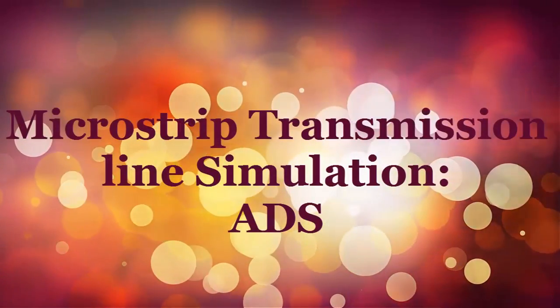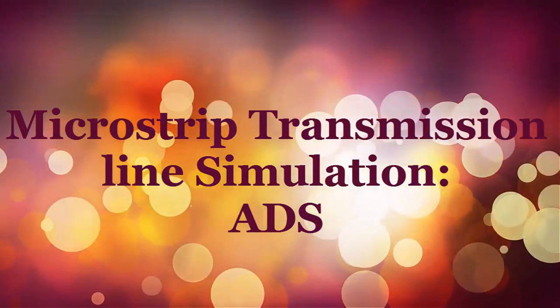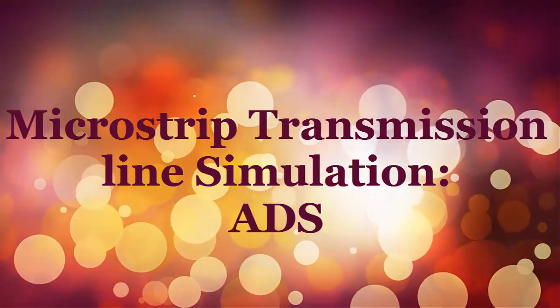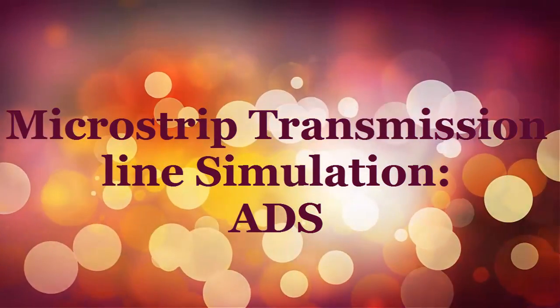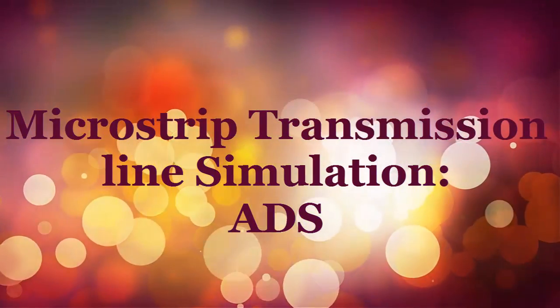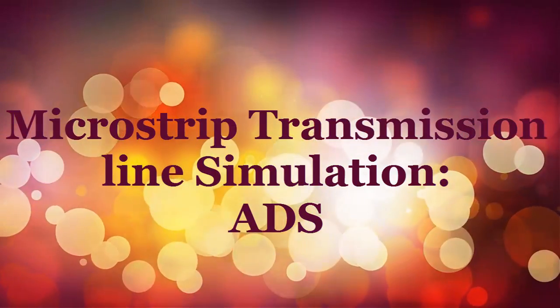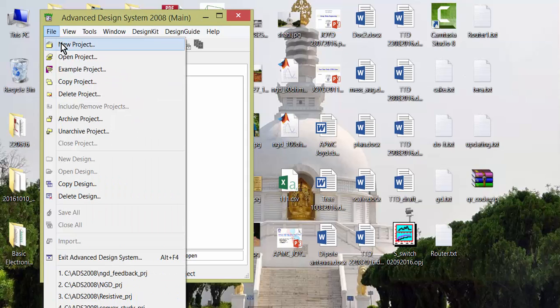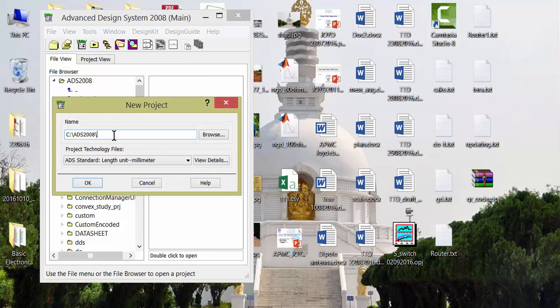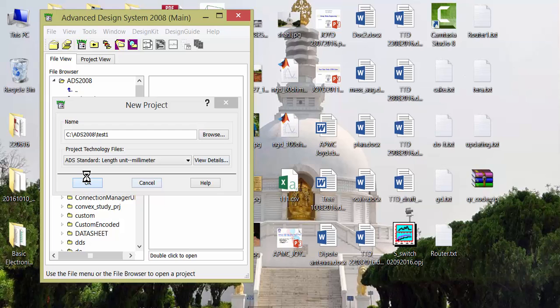Welcome. Today I am going to present microstrip line simulation in ADS, Advanced Design System, Agilent. Actually, a microstrip line you may consider as an ideal transmission line, or an ideal two-wire transmission line equivalent. In ADS we will simulate it and see how easy it is, including ADS full wave simulation, and that is Momentum. First we will simulate the ADS schematic, then we will verify using a substrate, and then Momentum full wave simulation.